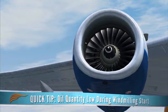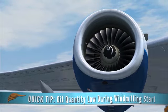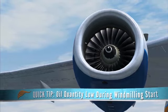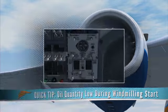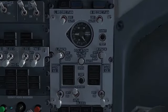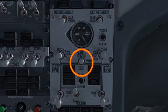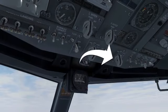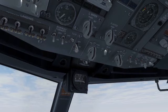Oil quantity indications may be as low as 0 during a windmilling start because of the lack of compressed air to allow the oil to return easily to the oil tanks. When the aircraft is out of the flight envelope for a windmill start, or when the engine has been shut down for more than 1 hour, a crossbleed start must be performed. This method does use the engine starter, therefore the engine start switch must be placed in the ground position. Neither form of in-flight starting has electronic engine control protection mechanisms.